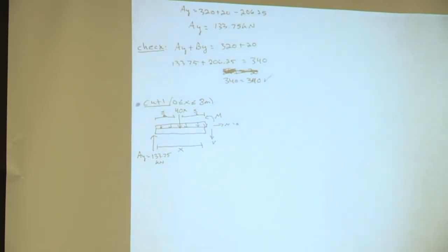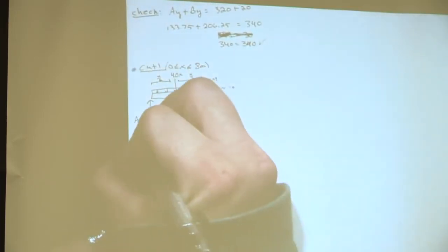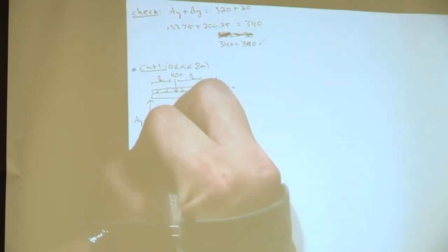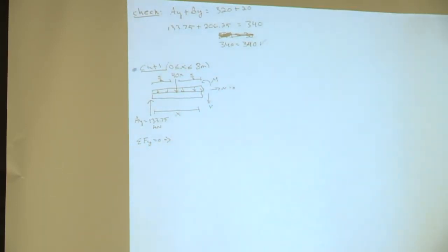Okay, so where do we go from here? Find the shear equation? Yeah. Okay, awesome. So how do we solve for the shear equation? Forces in the y direction. Awesome, so sum of forces in the y direction is equal to 0.